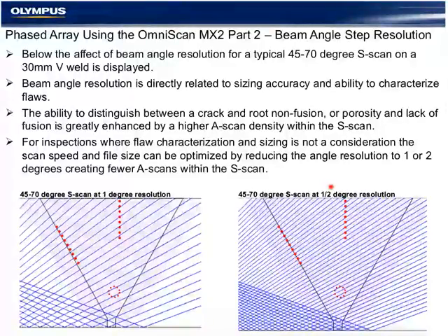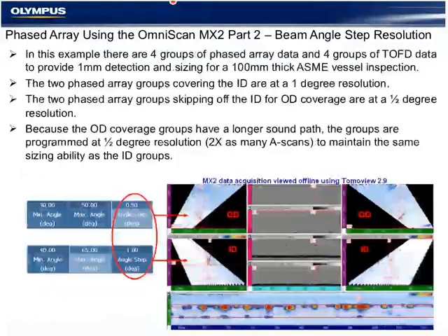In lots of our applications, it's not the bottleneck or significant, but we can see here with more A-scans, we're going to have a much higher resolution and a better inspection if it doesn't cause us file size or scanner speed problems. Again, more is better.